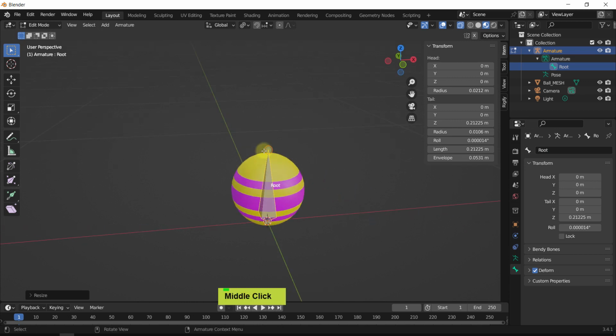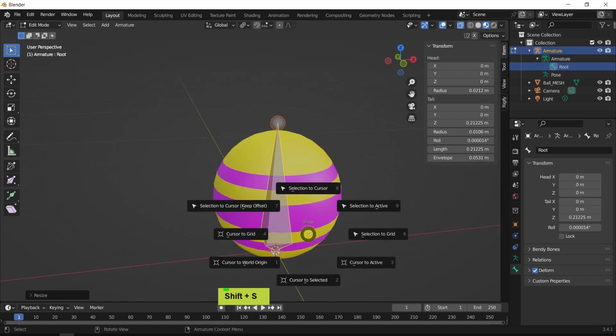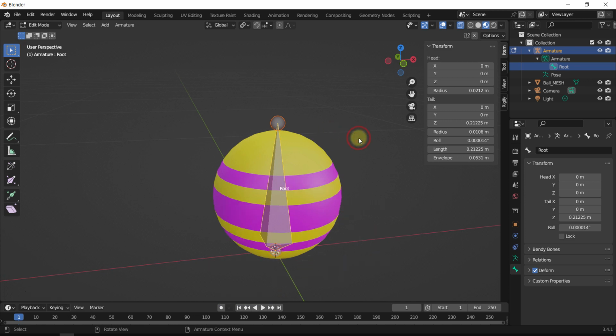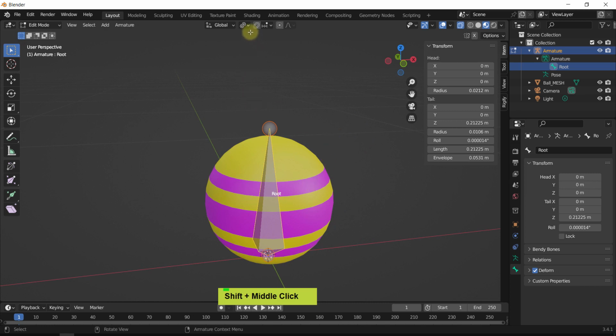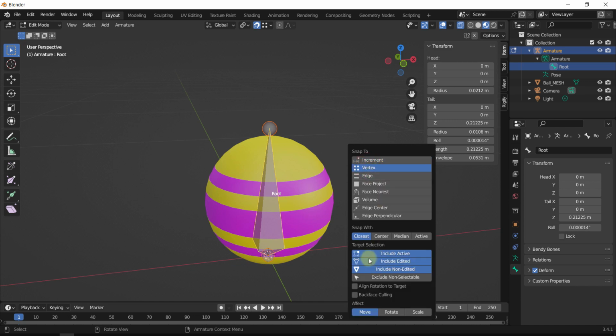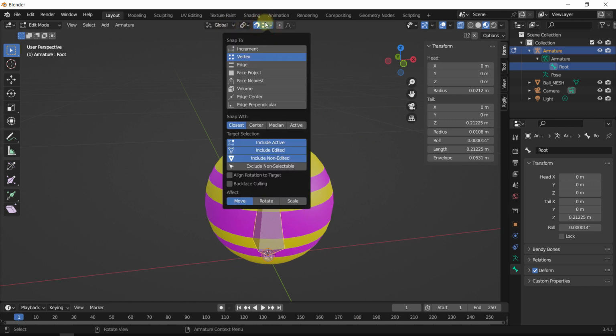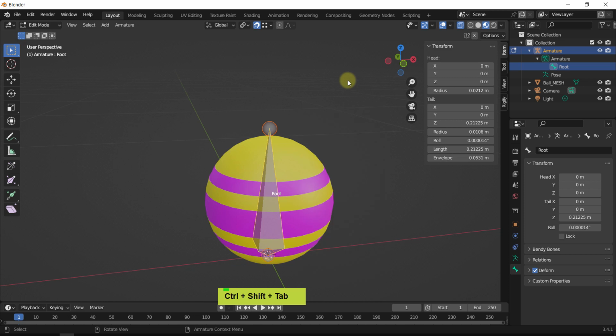Let me hit enter, and it updates in the viewport, and this is great. Okay, what else? We want to make it fit to the whole thing, and you can make it fit by using the Shift S and using the cursor and navigate with the cursor, but we have snaps, and the snaps are working like a charm. Now, but before we do the snap thing, first of all, Shift Tab will turn on snap by default. There's another hotkey, I'm not using it too much, but here it is. Ctrl Shift and Tab opens up the snap dialog, so we can switch directly here to vertex and closest and move, and that's it. And of course you can reach it from here. So this is Ctrl Shift and Tab. That's the hotkey for this.